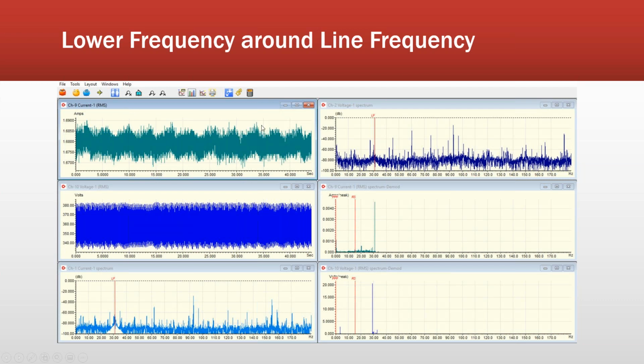Anyways, once the data comes in, I get my higher resolution, low frequency data. I get current, I get voltage, then I get a current FFT, a voltage FFT, and then DMOD. DMOD is there so I can identify my speeds and possible peaks. Do not ever use this to troubleshoot. It'll steer you wrong. You need to be able to reference to something.